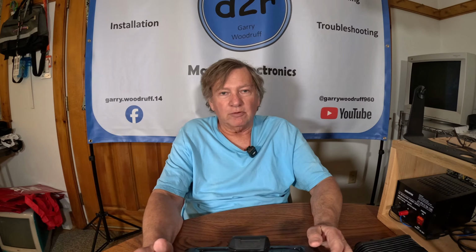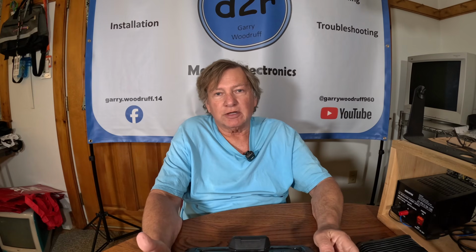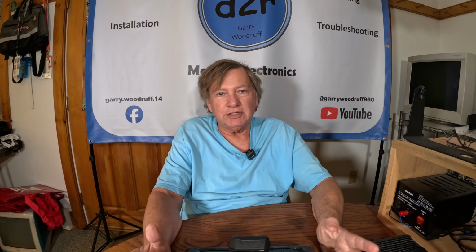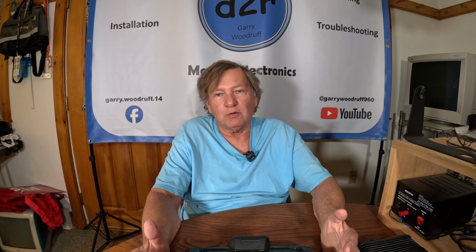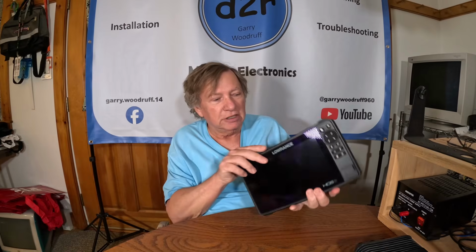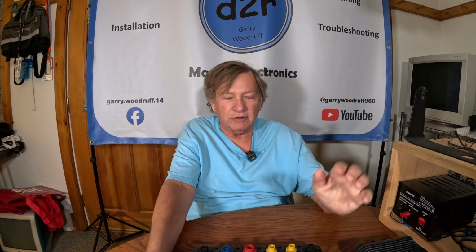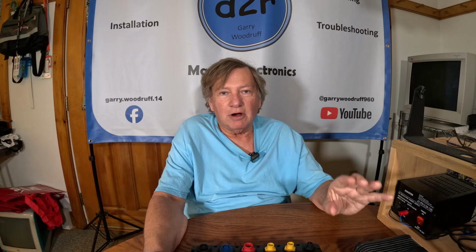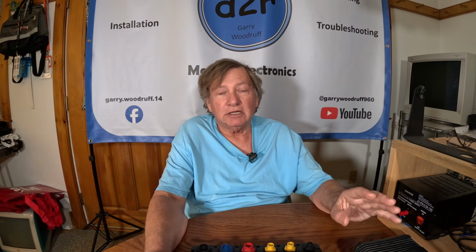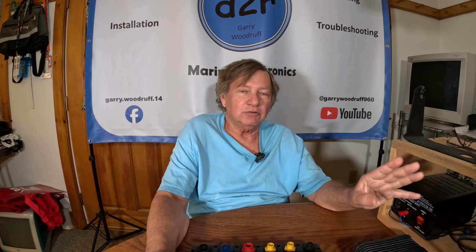Okay, long before the Ethernet got working on all the devices, I was using the NMEA 2000 bus to share my waypoints. One disadvantage of that is that it basically only shipped that waypoint. When I punched out a waypoint on a unit like this one, I'd hit the waypoint button, create a new waypoint, and it would then get shipped along the NMEA 2000 bus to the other units. The problem is those units had to be powered on, okay. If those units were not powered on at the time, that waypoint was never sent to all the units, okay.